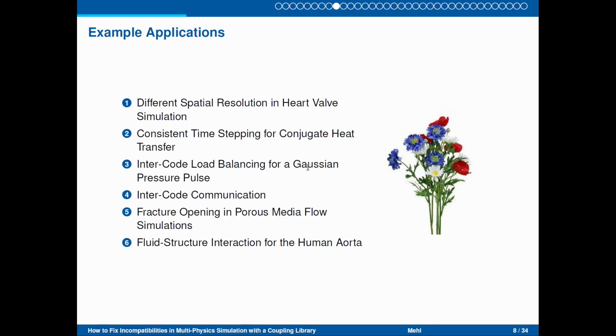And this is the generalized form in a multidimensional setting where you have thousands or millions of data at a coupling interface. And you see there's a lot of matrices. So this means if you have these formulas, you develop an algorithm which first of all is parallel and second never stores a matrix, but only low-rank approximations such that we still have linear complexity and scalability.